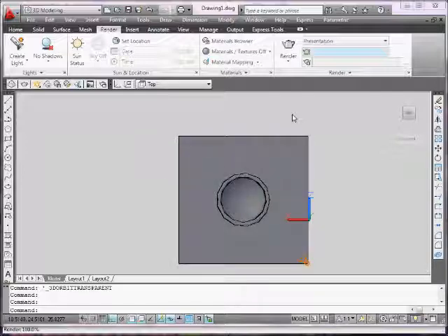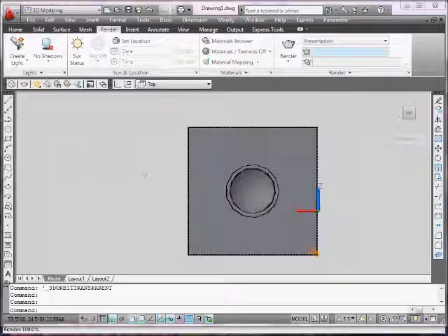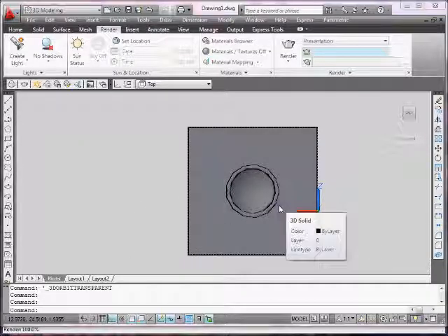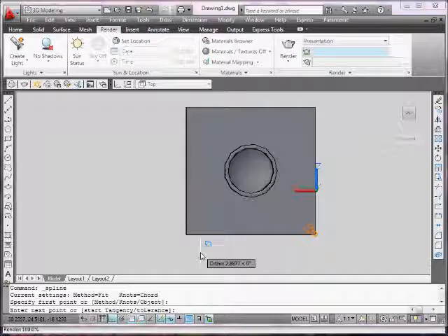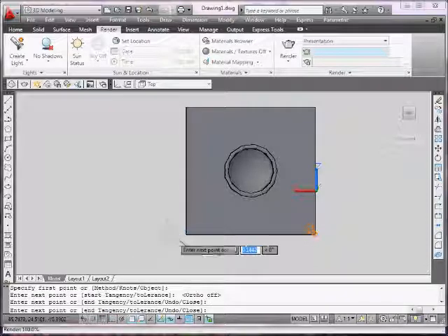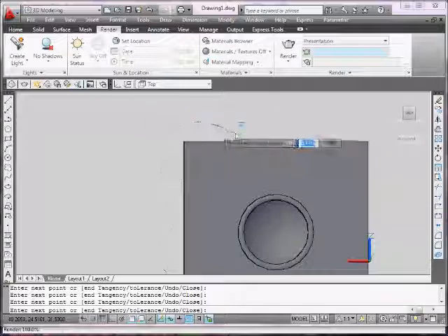I'm going to draw up my curtain, so I can view it with my light. If my light's facing this way, I want to make sure my opening is over here, and so forth. Of course, you can rotate your curtain so you can put it into position where you want it. I'm going to make it a nice design by using the spline command. I'm going to start it from around here, turning off my ortho, and making it wavy, because usually curtains are wavy. So, oops, I'll fix that.